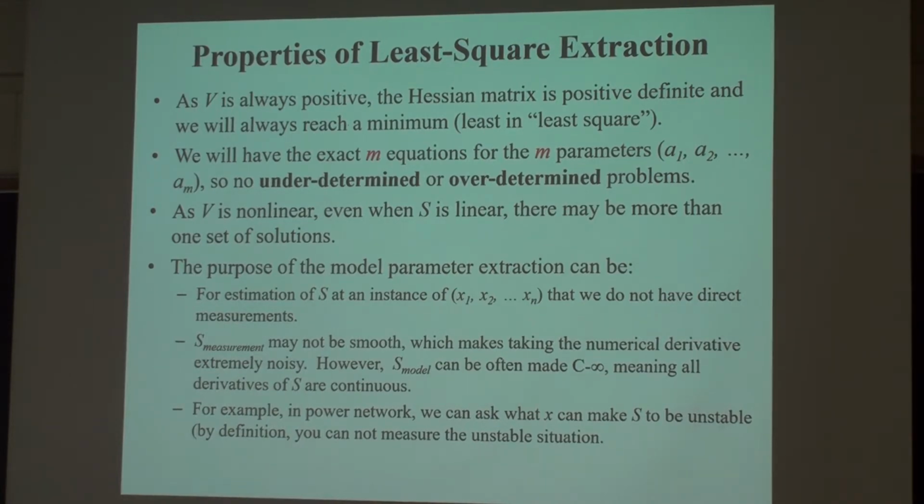Noise and uncertainty in the things that you measure is one thing, maybe small. You take a derivative, you are totally dead, right? If anything is noisy and you don't do anything about it, you just take a derivative of two points. Two points contain noise, then there's nothing you can say about that derivative.